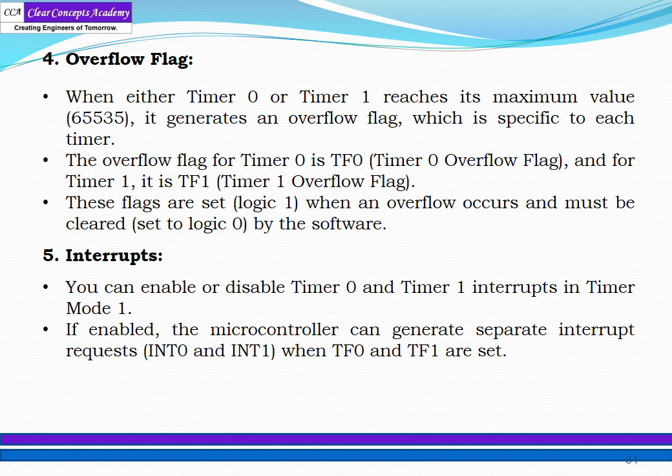If enabled, the microcontroller can generate a separate interrupt request for INT0 and INT1 when TF0 and TF1 are set. When overflow occurs, it will generate an interrupt 0 request and interrupt 1 request if those interrupts are enabled.